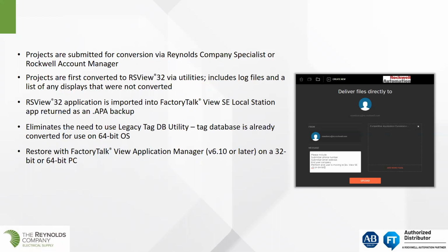And these projects are first converted to RSView32, and the reason is these older InTouch and iFIX applications are constructed in much the same way as an RSView32 project was constructed, based on the older, I would call them 1990s, HMI technology. So it's much easier to move to RSView32 first before we move along to FactoryTalk View SE.